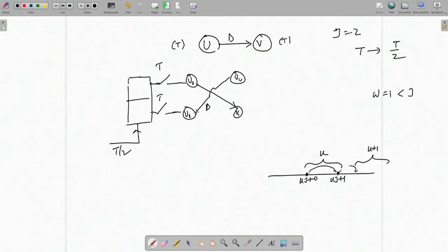But here you see this edge has got one delay, but as I told you, if W is less than J, as is the case here, edges in this downward direction become delay free. So, it is delay free, which means this time t and time t, they get added, not for this edge, but for this edge, because I have to take the edge which takes maximum time. I have to go by that, because I have to give time for that also to be completed, not only the other one. So, this edge will require t plus t, 2t. So, system clock cannot be made shorter than 2t. That means, instead of 2t, it will become 2t, and then 2t by 2 means t.